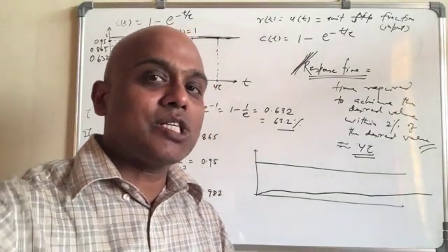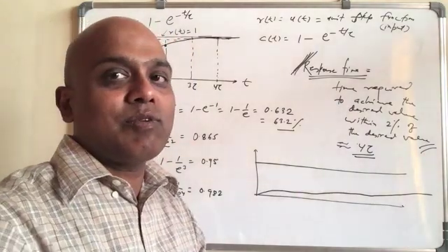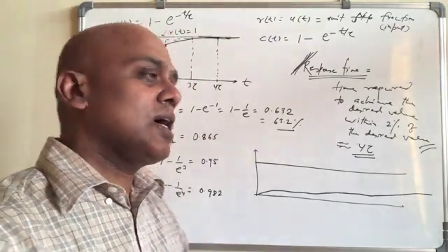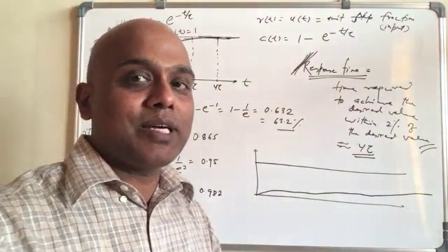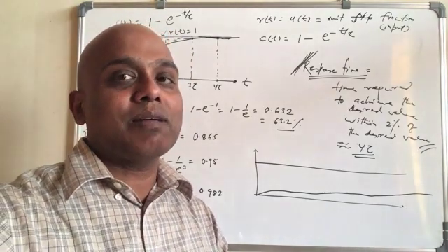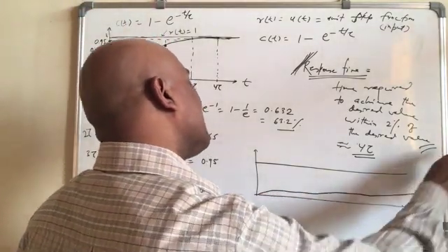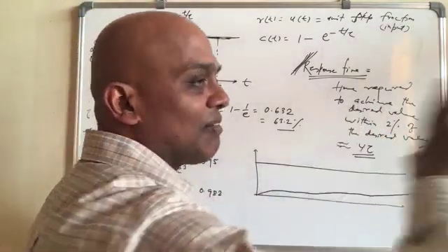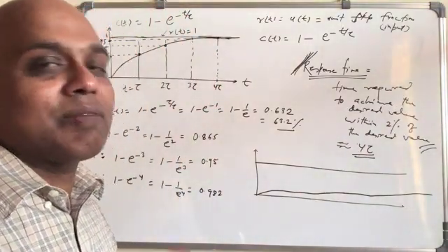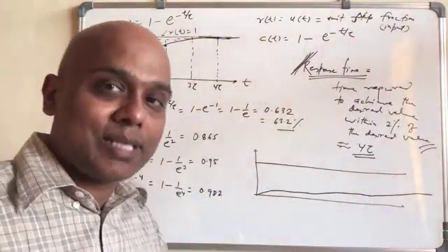When you switch it on and set the temperature from the room's 15 degrees Celsius to 25 degrees, the heater starts, but the temperature does not rise immediately. It is very slow before getting close to the 25 degrees Celsius you set. That means the response time is very large in that case.